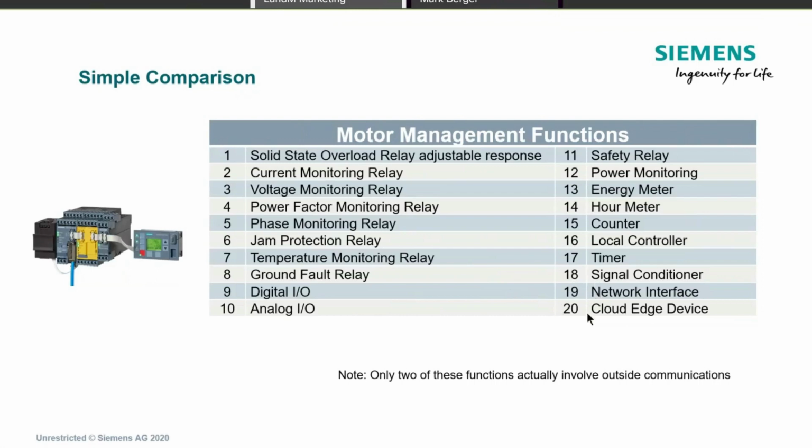The last item that you probably came here for, as we talked about, is the cloud and maybe an edge device where you're accumulating data. How does the SIMOCODE talk to that device or pass all these motor management functionalities and information up to a cloud device? Well, the SIMOCODE comes with OPC UA built in on the Profinet version. And I'm going to demonstrate that real quick. So I'm going to switch over to the programming software for the SIMOCODE, which is TIA Portal.